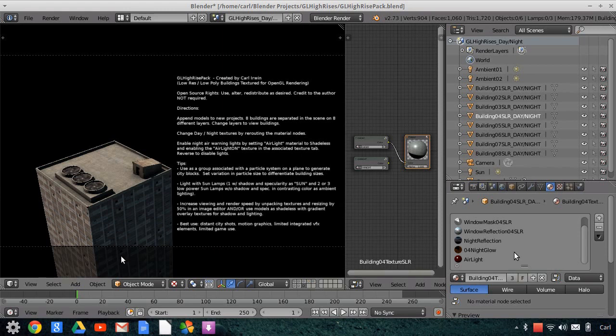They start on frame 1, end on frame 1, and then you apply the group as the object to that. You can change the size of the buildings and the rotation to be upright, and you can also add some variation to the size so that the buildings are not all the same size. But anyway, that's how that is done.